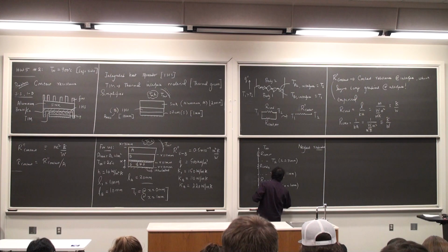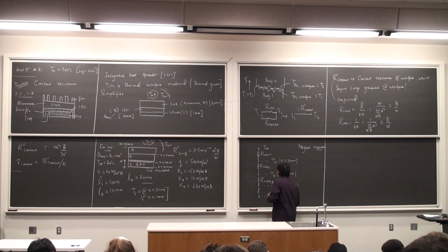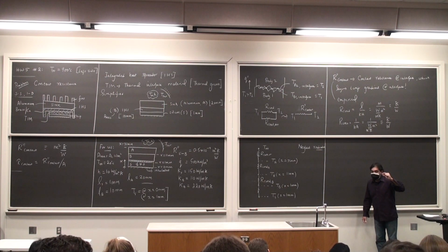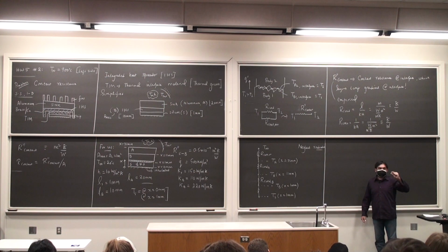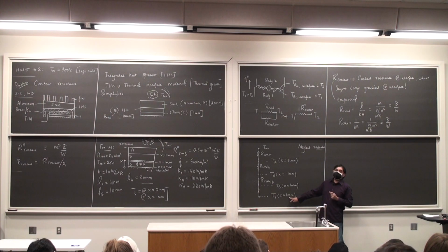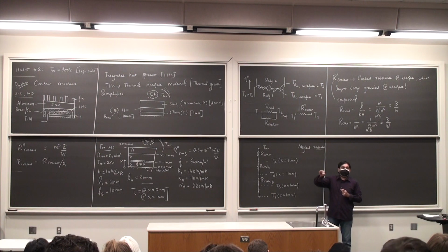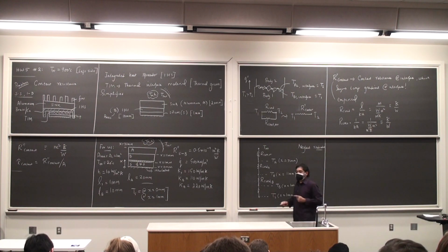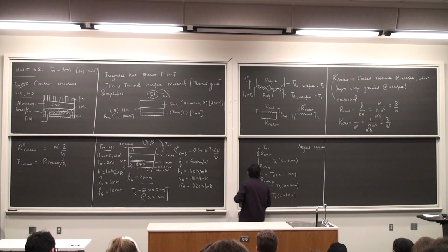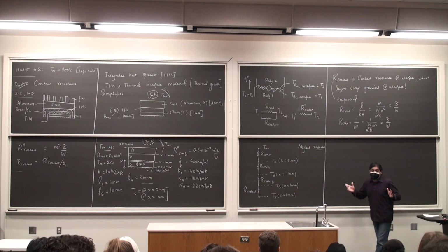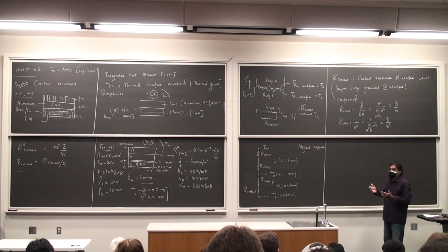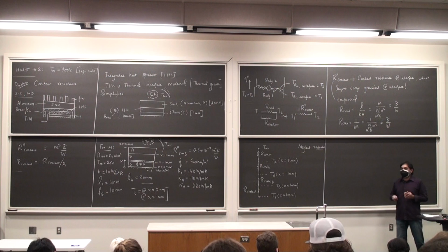The silicon, please notice, we are assuming that this contact is infinitesimally thin. Which means I am still using x equals 1 millimeter at the contact region, but there is a small resistance or a small temperature drop between the two. So this is our contact. That's about the only network I can draw. I cannot go further and draw through the silicon chip. I have to do the heat diffusion equation inside there.